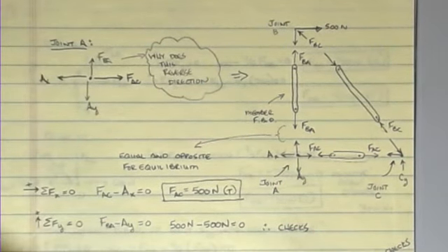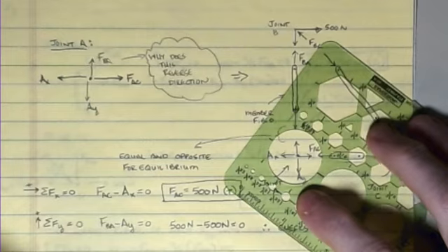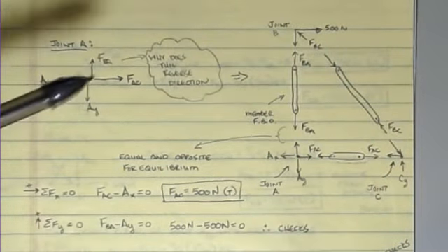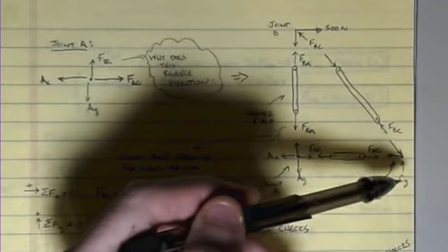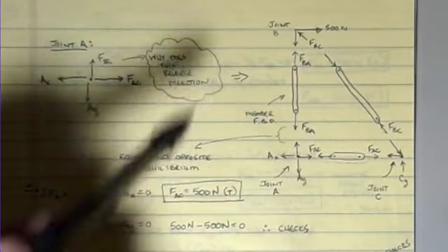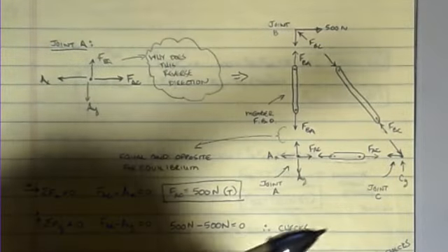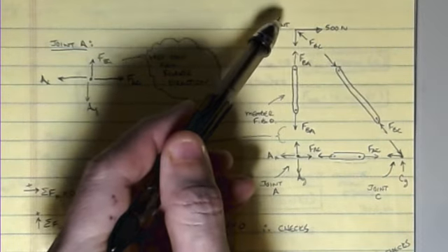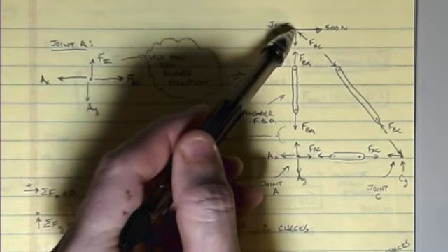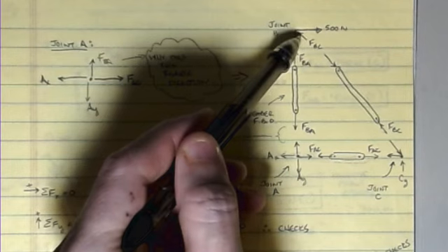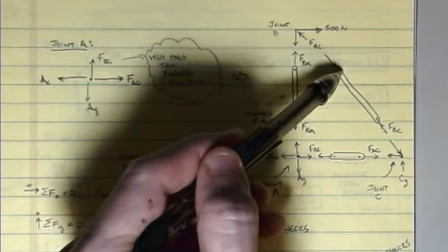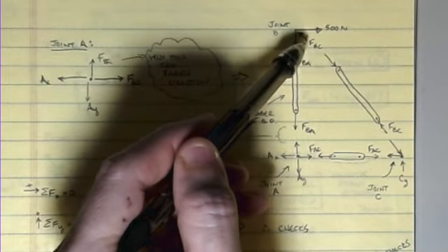We'll basically be drawing a free body diagram around that joint as we look at part of our structure. Typically we don't draw all of them at one time, but I'm going to show you these because I want to show you how they work together. Here I assumed that FBC was a compression member pushing up on this joint. To balance this, if I drew a free body diagram of the member itself, I would have an opposite arrow pushing on the end of it, because these two have to be in equilibrium.